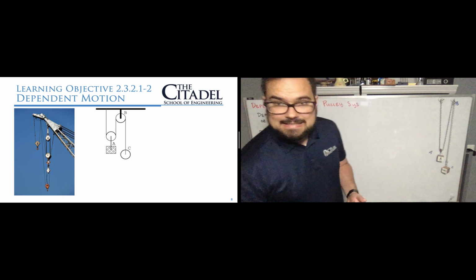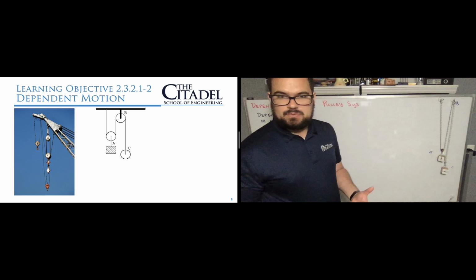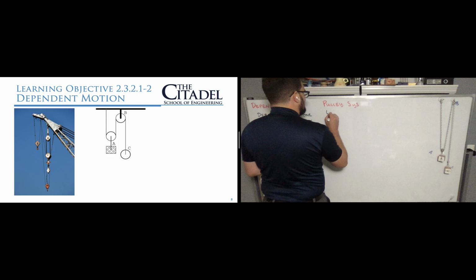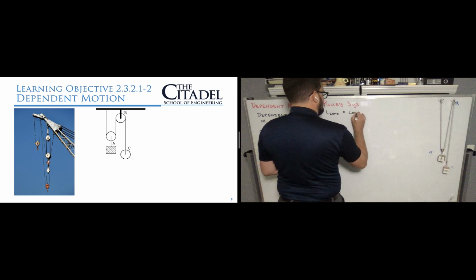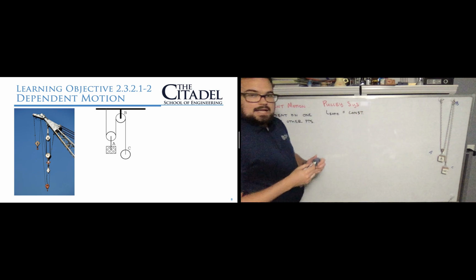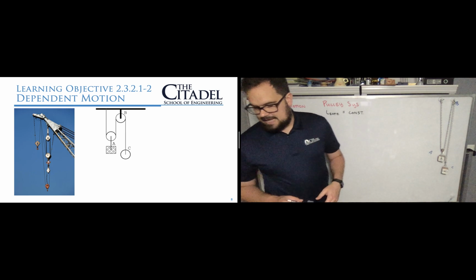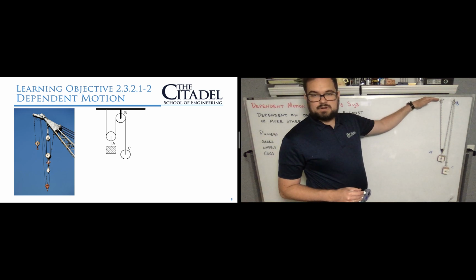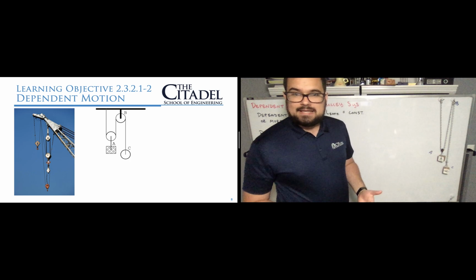When we think about the dependent motion, the idea is that if I move C, A is going to move, and there's going to be some relationship between those two. So when we think about pulleys as a system, it's all built on the idea that the length of a rope in a pulley system is a constant. If you look at your book, the chapter on pulleys basically says, if the rope's length is constant, then we can set up a datum, an origin point, say where all the fixed points are, and if we look at the length to where each point is and add that up, that total length is going to be constant.